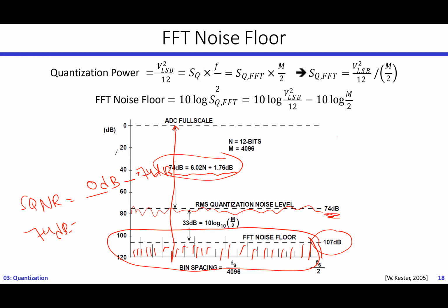If I am distributing it to, let's say, a 64-point FFT, I will distribute it to 64 bands and they will have a higher level. If I do this with, let's say, a 1024-point FFT, they will go to a lower level. So the average will be lower, but the total amount will stay the same. And that is basically the difference.